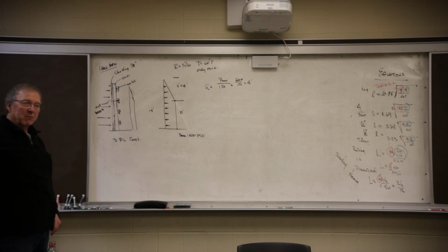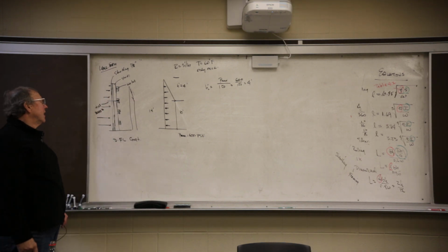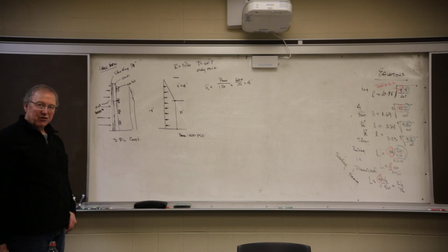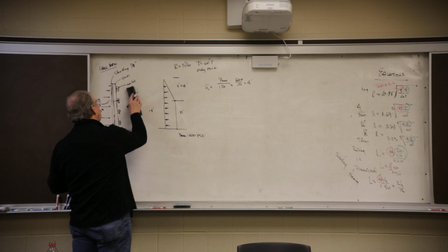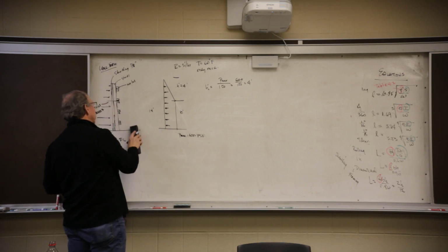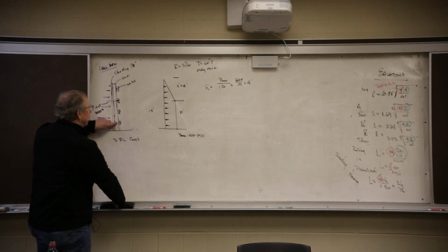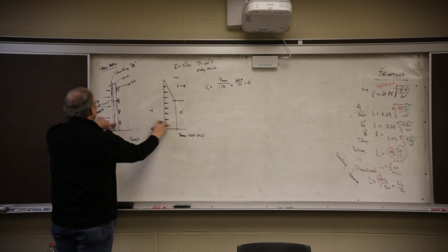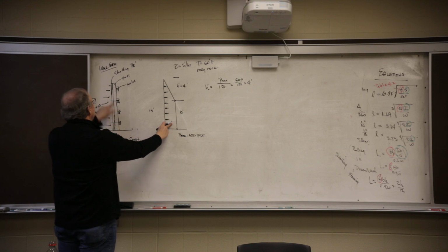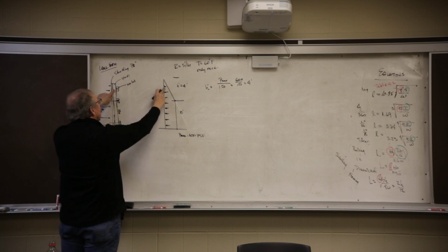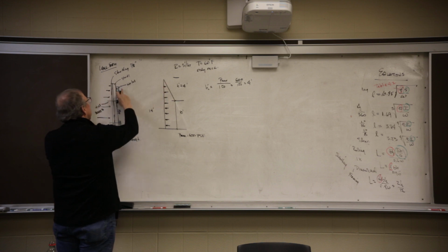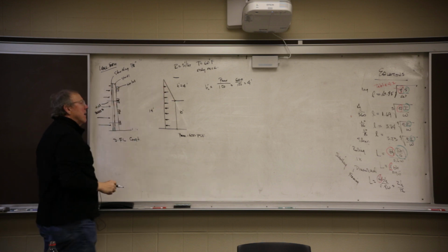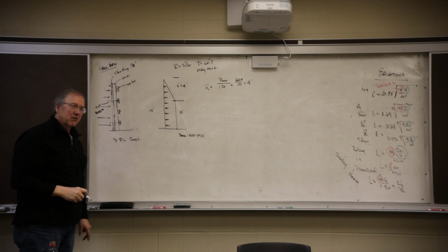They don't manufacture them like that. The studs are based on P max. Now, if you look at the wales and the wall ties, look at this wale. If I have a wall tie right there, the pressure is really big. If I go up to this wale, it's at a point where the pressure is small. And if I had a wall tie here, the pressure is small on the wall ties.